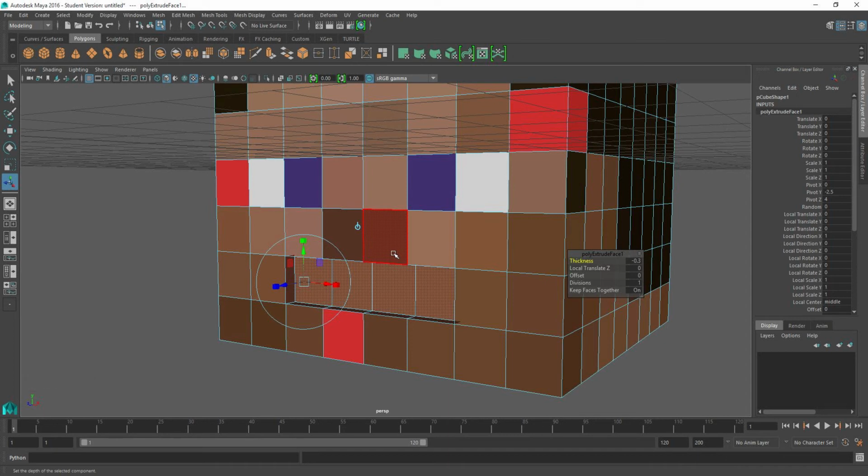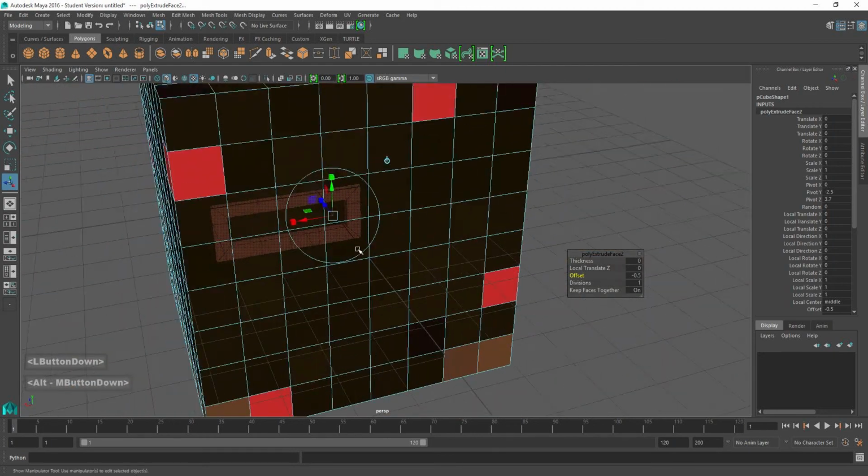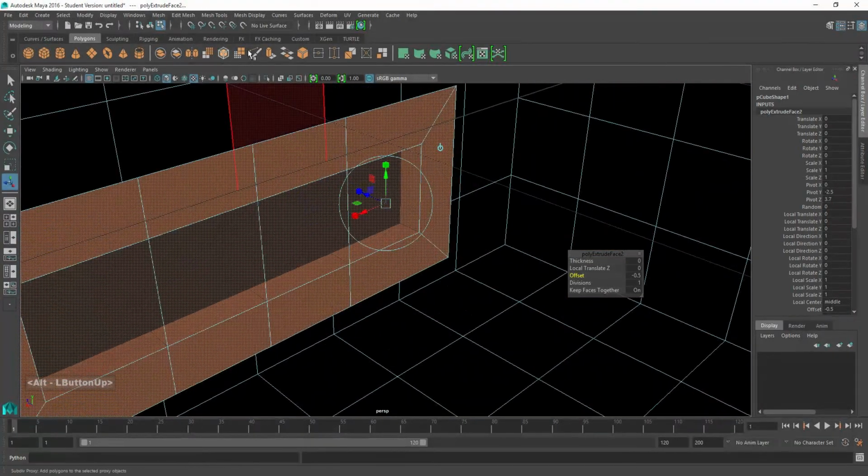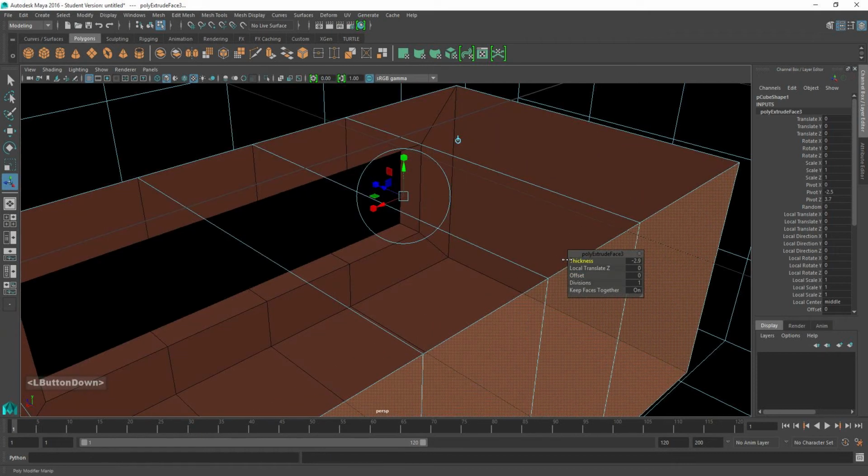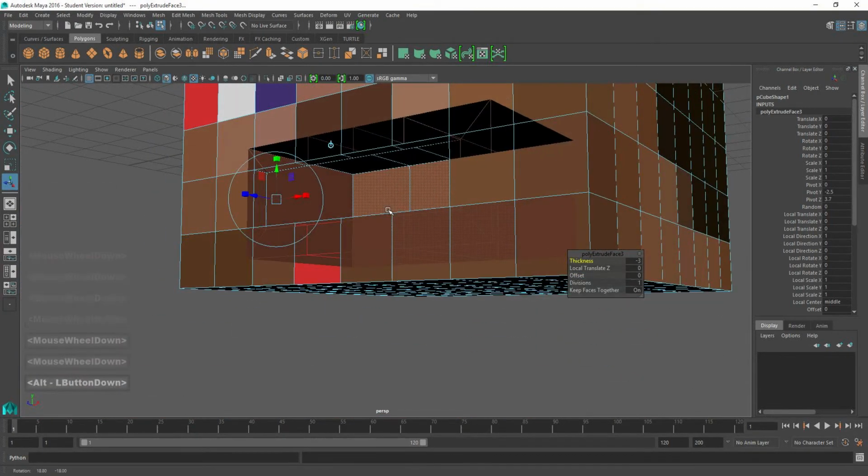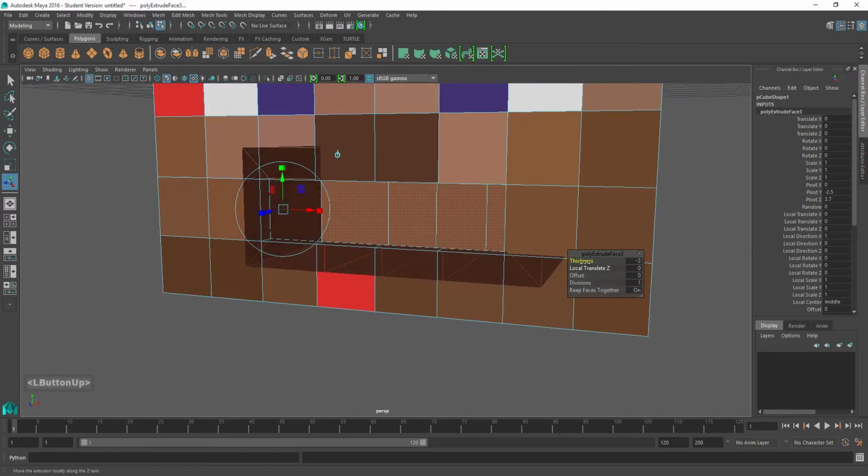Here you can choose if you want the mouth to go to the inside of the head as well, or if you just want it to stay like this. Or if you want to delete it, you can make a separate mouth. But for this tutorial, I am going to extrude it a couple of times and not make subdivisions, but do the offset a little bit into the inside of the head, like so, and then extrude it again and make sure the thickness is about 3. Or maybe if you want less, you can go for about 2.